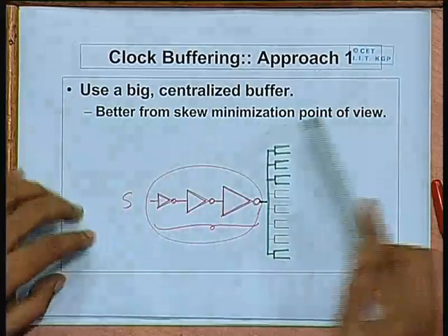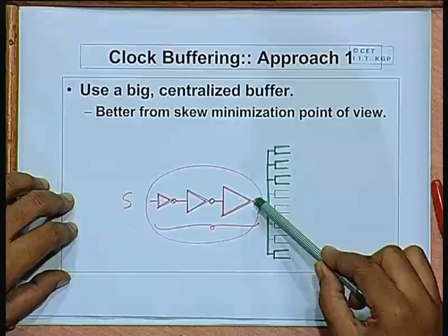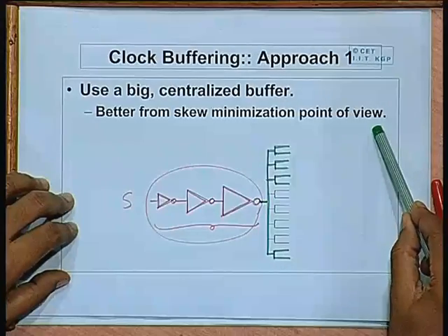But of course, one problem with the passive interconnection network is that if these lines are pretty long, then again the signal degradation will occur. Well, if you are careful with the total length of these lines, skew can be controlled, but signal degradation is there. If the rise time and fall time degrade significantly, then also you have to keep some tolerance in the clock period. So, something similar to clock skew also occurs. So, the speed falls.